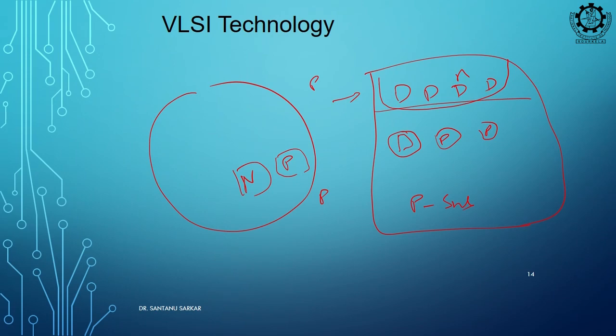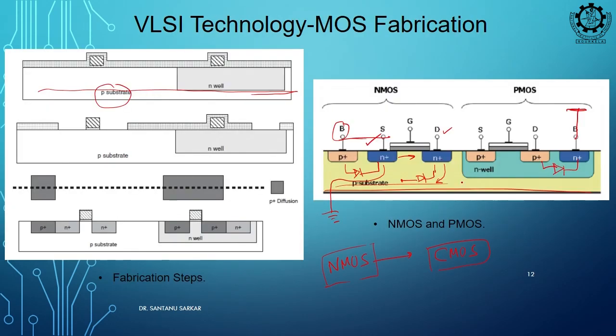So, all the substrates are actually shorted. In NMOS you have no options, you can only connect to the substrate, which should always be connected to ground, because this P substrate is common for all the NMOSs. So, one NMOS at voltage V1 and another NMOS substrate at ground is not possible. Your tool will give a warning, right.